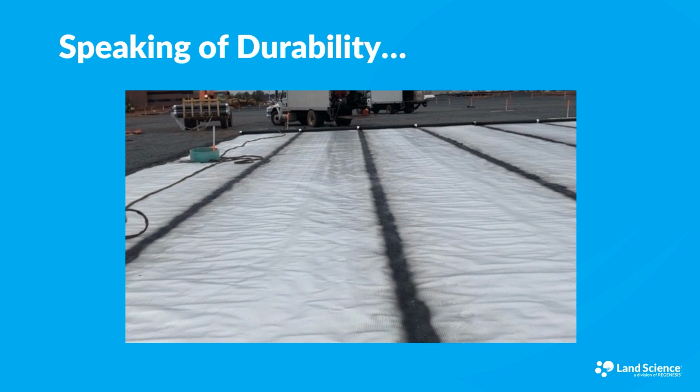But as it turned out, none of that ended up being true. As you can see here, the barrier system was untwisted and pulled back into place. The nitrile advanced spray applied seams held everything together across the entire system. Only minor repairs were necessary. The applicator completed a smoke test as part of our QA/QC process to ensure the integrity of the installation. Using a barrier system with spray applied seams over a tape system saved what would likely have been significant delays and additional costs to the project.